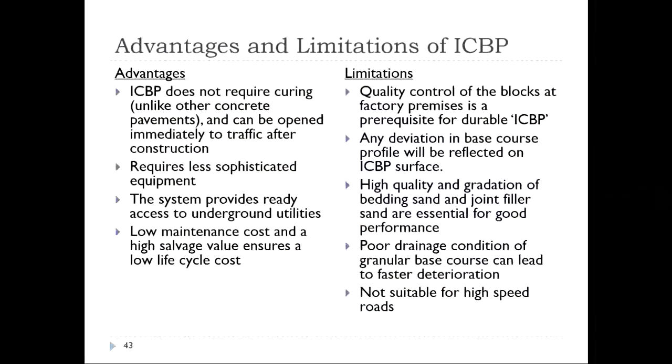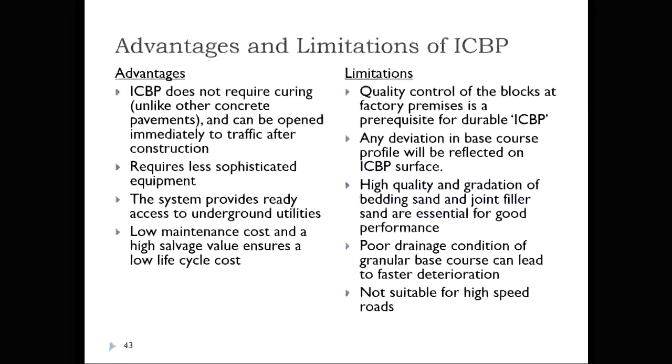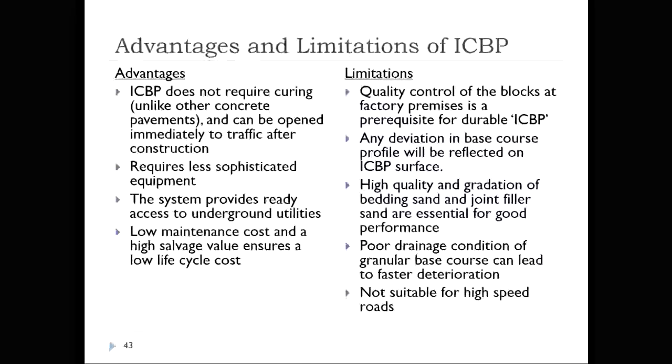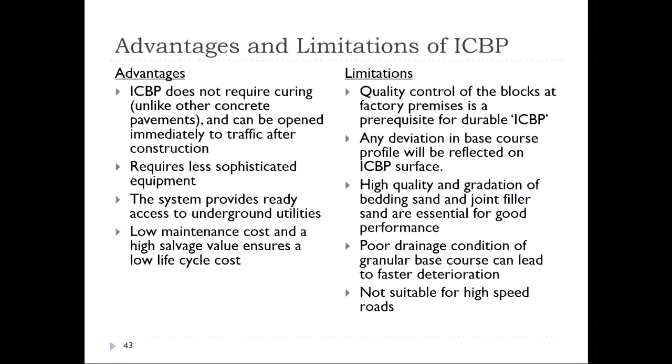Now, I have just compiled the advantages and limitations of interlocking concrete block pavements. Interlocking concrete block pavements do not require curing, unlike other concrete pavements. Say, all the other three concrete pavements we discussed previously, for example, the first one was short panel concrete pavement, or self-fill concrete pavement, or the roller compacted concrete pavement. All of them require a curing period, so you cannot open the road to traffic. Here, in the case of interlocking concrete block pavement, you could open the road to traffic immediately after construction.